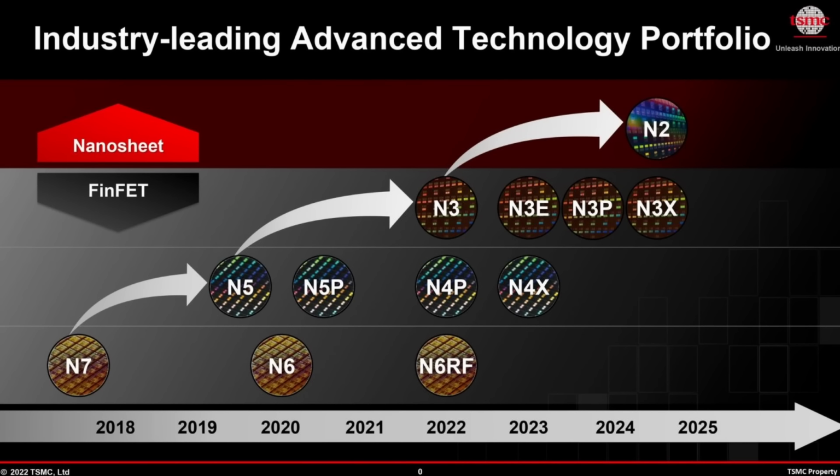Smaller cells take up less space and use less power, but also provide lower current. Larger cells provide higher currents, but use more power and need more space. It's always a trade-off. The reason why engineers are creating these different versions of the same logic gates is that different areas of a chip have different clock speed and current requirements. If we are selecting a standard cell to use inside our high-performance CPU cores, we want to select the extra beefy implementation that can handle very high switching speeds. Our low-power efficiency cores, on the other hand, can do with the normal cells. We save power and silicon area at the same time.